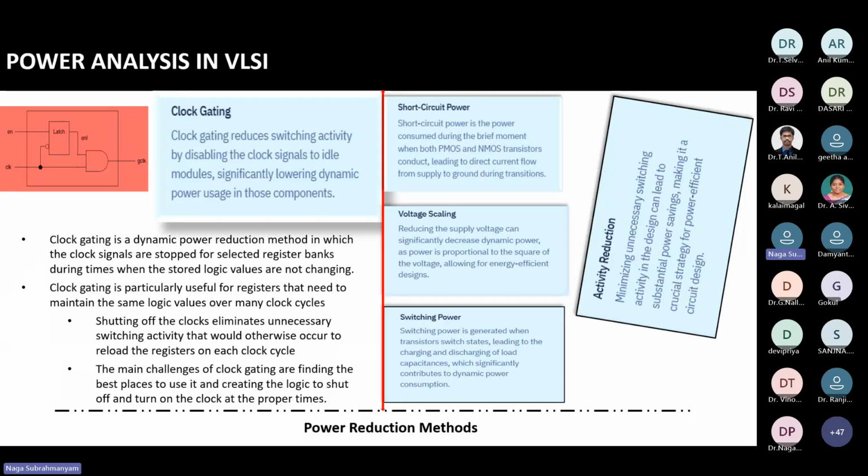That is what voltage scaling means. The fewer voltage domains you have, the less you need to scale the voltage from one domain to another many times. And as the power changes from one domain to another domain, we need to switch the power, right? For that switching, there are some techniques. By using those, we can reduce the power.